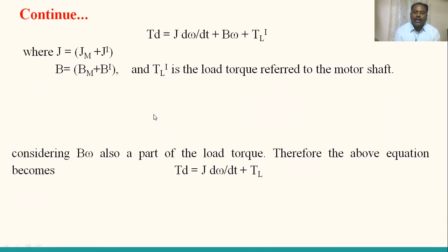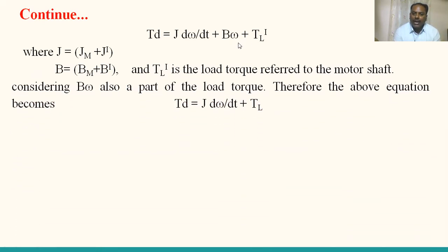Considering Bω as also a part of the load torque, the above equation can be represented as TD equals J dω/dt plus TL, where TL is equal to Bω plus TL dash. That is the reason Bω is also a part of the load torque. Yes, this is the equation.